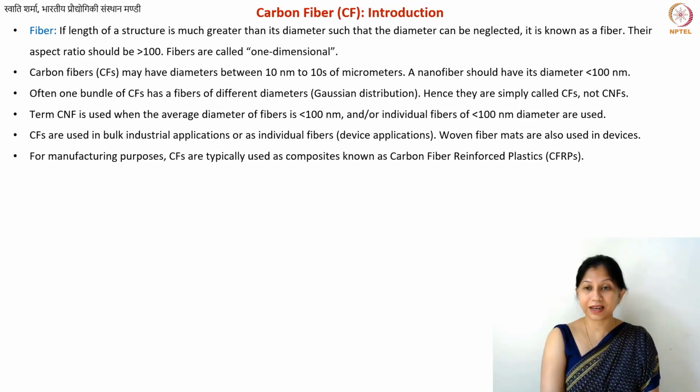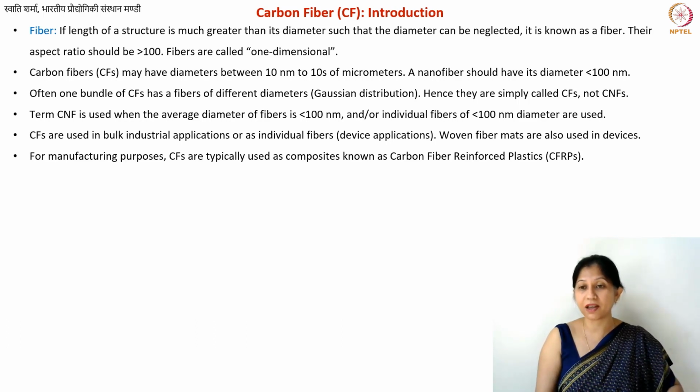And why do we need the resin? In most cases, when you are doing this weaving of carbon fibers, you need some sort of lubricant. It's easier, otherwise you may end up damaging the surface of the fibers. You may even end up breaking a lot of fibers, because they are, after all, made of carbon. They are hard and brittle. But once you have a lubricant, once you have a resin, then the weaving is easier. And that is why we often use these